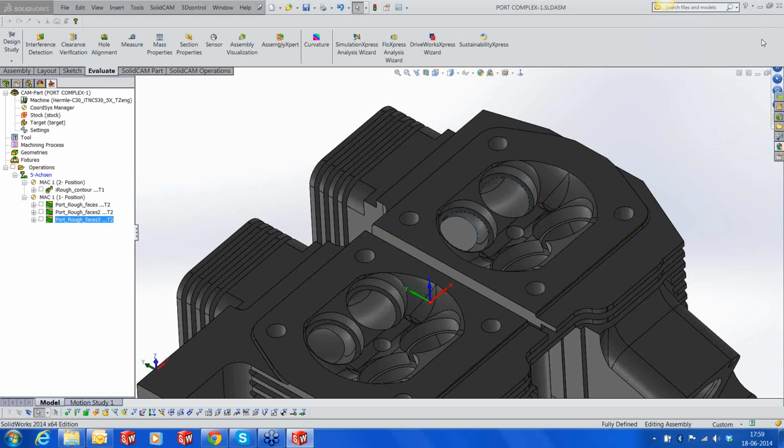Sorry, we're going to do the finishing operation now. And in finishing, we have got 2 options. One is spiral, and the other one is along. Spiral is a more common way of cutting, but in some cases, the customers are very particular about the flow direction of the gases. So your finishing must follow the direction of the gases.